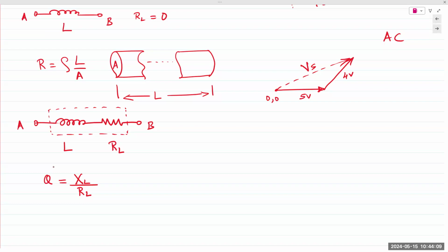Yes, that's what we're doing. We are simulating a bad inductor. Otherwise, we would not be able to perform that experiment. Okay. And then we do that again. So if your instructor requires you to add an RL to a bad inductor, then you'd have two resistors in series. One is internal to the inductor, one is external. Okay, so keep that in mind.